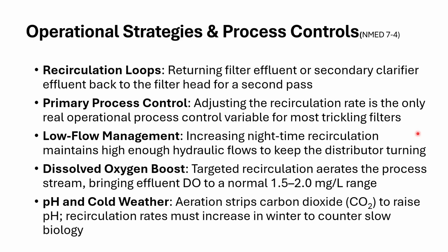That's what's causing that arm to move. Well, if the flow is so low it can't cause that arm to move, we're just going to have a little trickle over one part of the filter. We want this wastewater applied uniformly throughout the filter media. So we're going to increase that recirc rate at night so that we have enough energy in that trickle to move that distributor arm around.